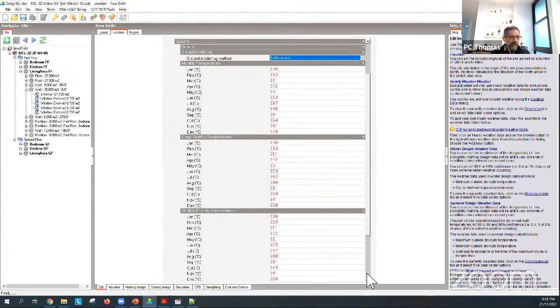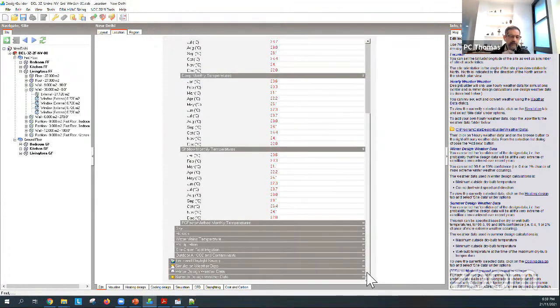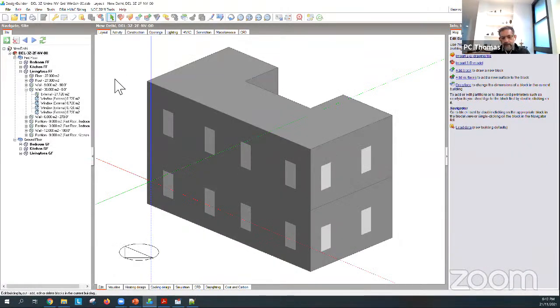Okay. Why is that important? Because if you're in a cold location, particularly, or cooler location like Delhi can get pretty cold in winters, then the cooling demand will be suppressed and the heating demand will not show correctly if you don't have the right ground temperatures. The reason this is a very difficult topic, and you'll see lots of research papers on it, is